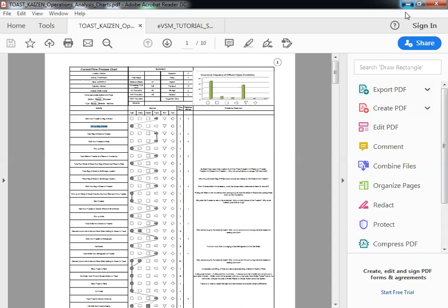So my suggestion would be that the flow process chart is more of a, let's look at the material flow first in its current state. Let's recognize all of the non-value adding steps, take them out. What is left will be your value adding steps. That is what you would put in the value stream map.